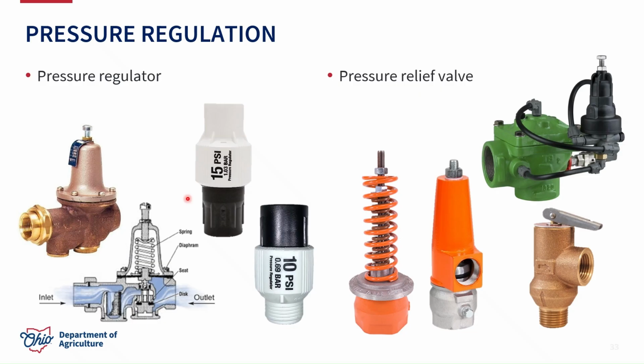Alternatively, there also may be pressure relief valves throughout the system. These pressure relief valves prevent the system from experiencing overpressurization from a closed valve or a plug in the system that may damage some of the components. So rather than that pressure building up, when it reaches a certain set point, this relief valve is going to release that pressure and protect those downstream components.